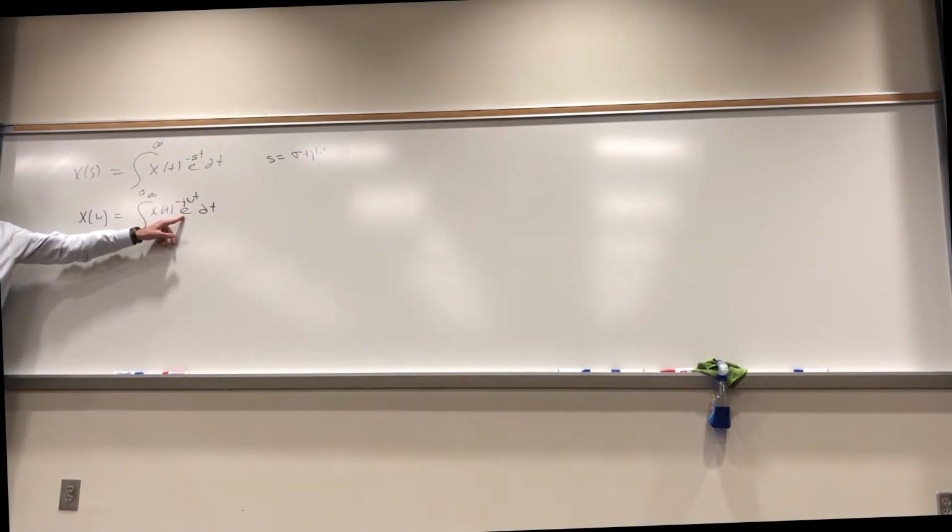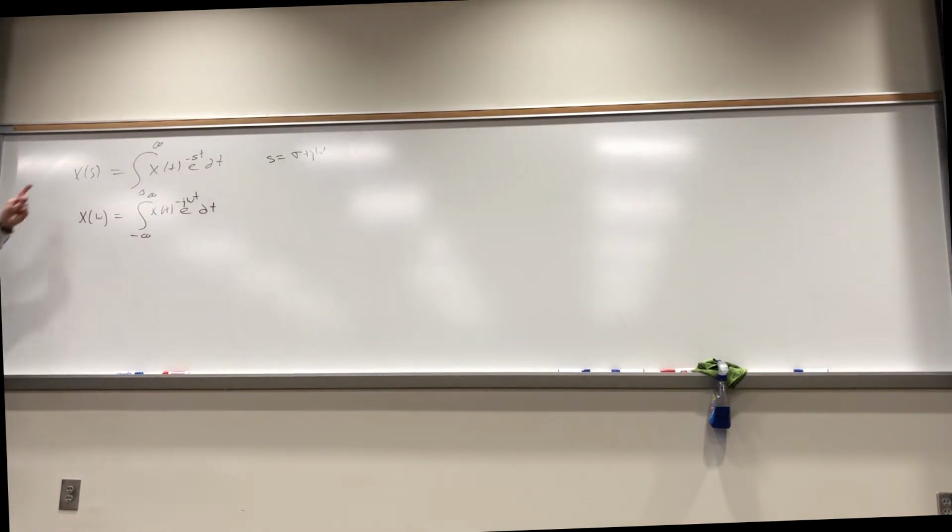There's no sigma involved. Follow me? So sigma is 0. But it also means any Laplace transform you have of a signal that's only for t greater than 0, you can get the Fourier by just letting s be equal to j omega most of the time. There are a few minor exceptions that have to do with one condition.